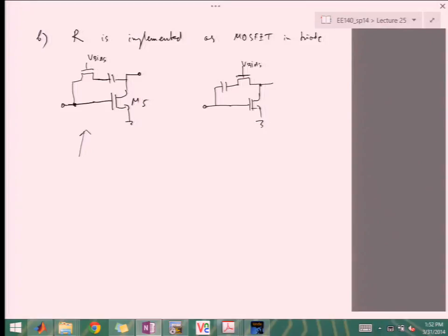Not just what's the bias voltage, but which arrangement is kind of more accurate, I would say, right? Because you put this transistor in and you bias it, you want it to emulate some R, right? For example, you want it to be greater than 1 over GM5 and turn it into left half plane. So as the circuit's working, is that always going to be the case? What if that transistor is not always with that resistance? So what affects the transistor's resistance? I guess that in these two scenarios, that's what you should be looking at.